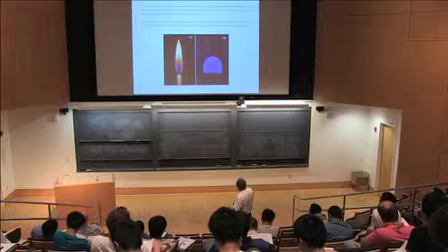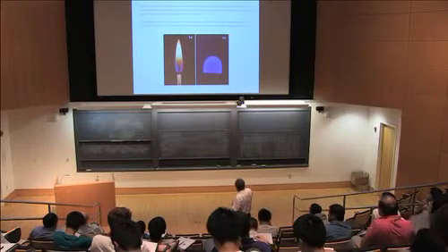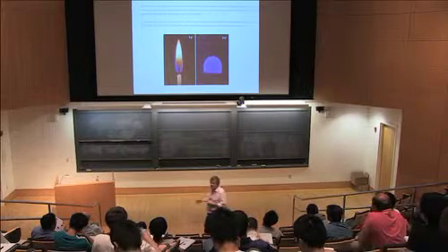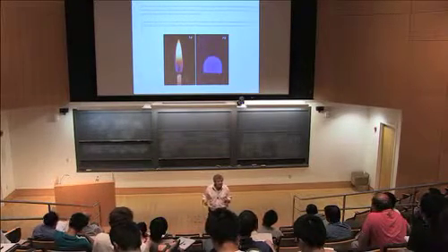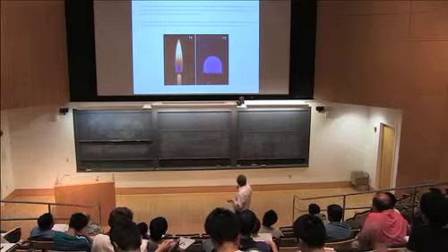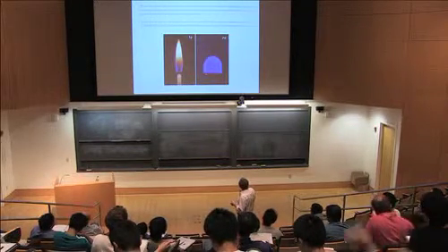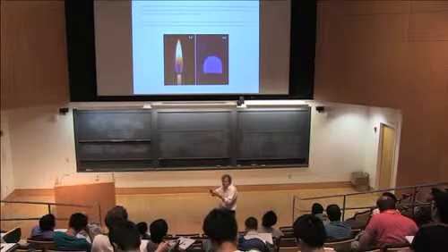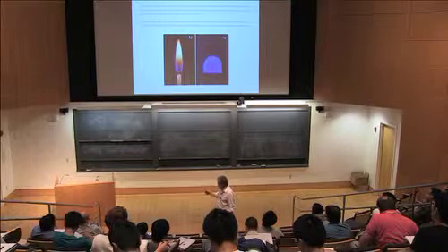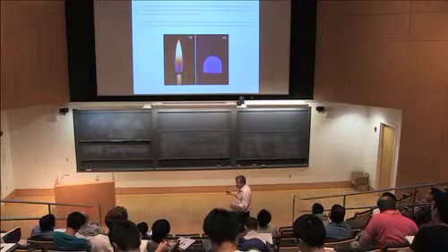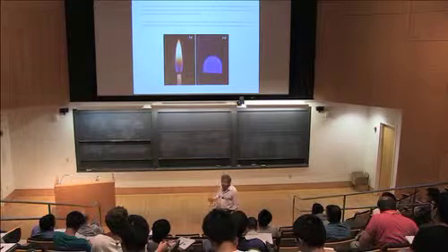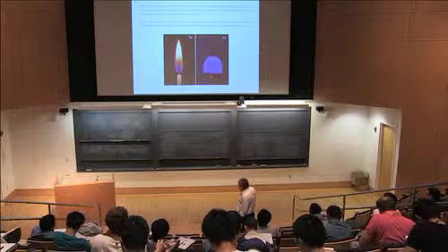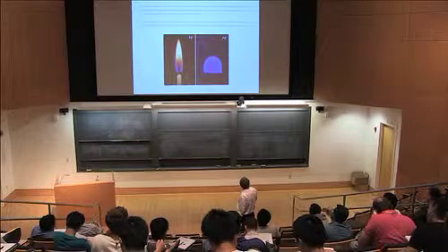So here is, in fact, an interesting picture of a candle flame that is burning at zero gravity. This picture was taken in the space shuttle by people at NASA. And what is interesting is that even in the absence of natural convection, just by diffusion, the fuel and oxidizer can meet and react. So the mechanism here is purely diffusive. Diffusion only.